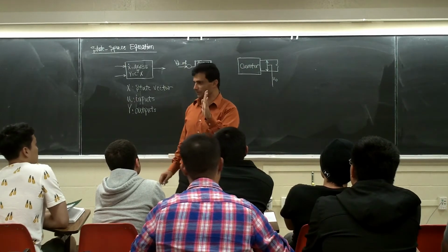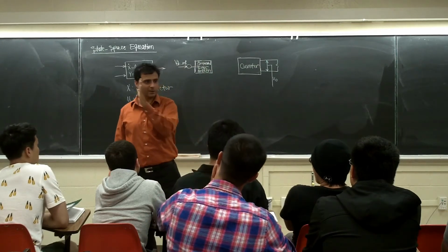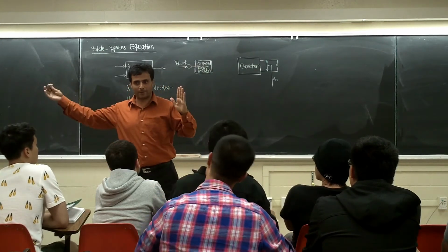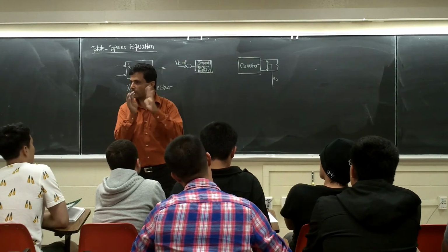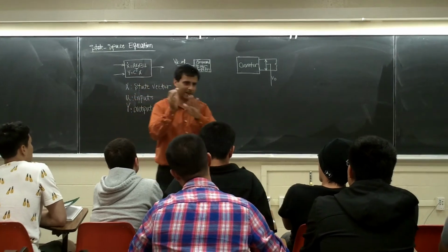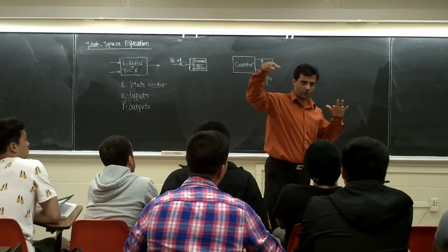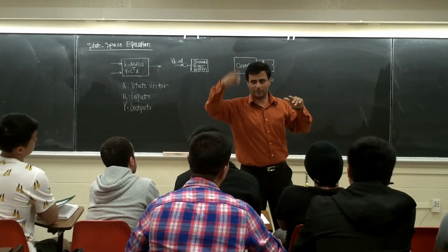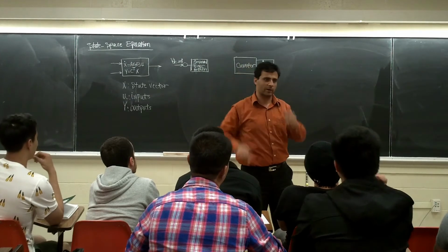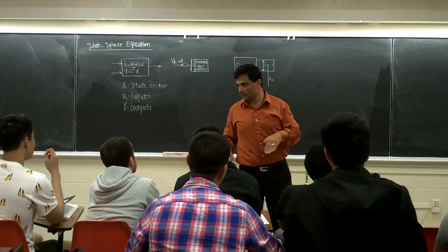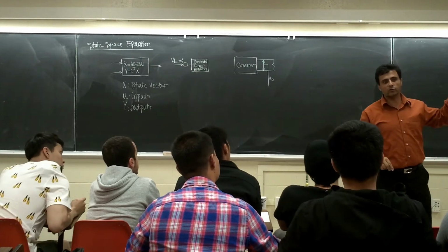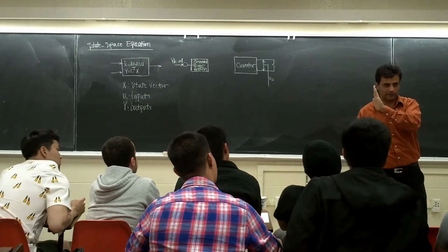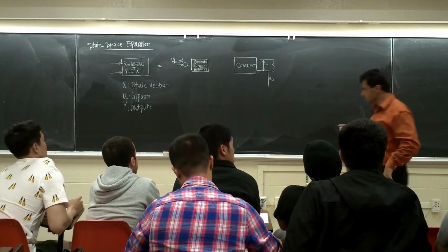They call it the sampling frequency, right? So the bigger the sampling period, the less bandwidth, right? Why? Because you don't know what's happening in the middle. You're missing that part. You're assuming it's going to come through here. At this point, I'm going to sample another one, do my calculation, and change my control values. But the analog system is continuous. It's doing it every moment, so the bandwidth is much wider.